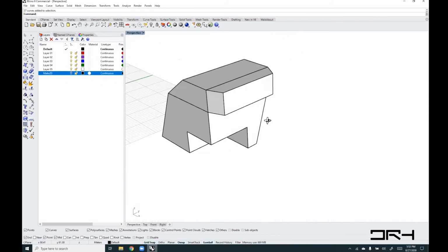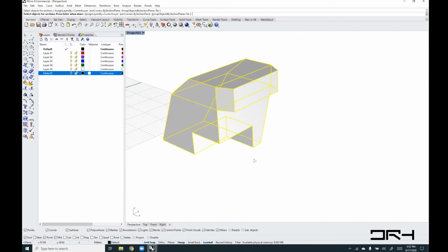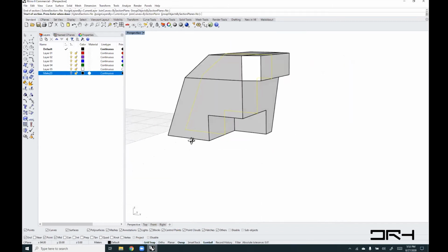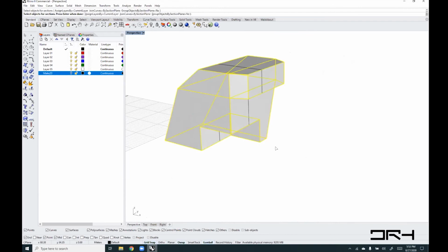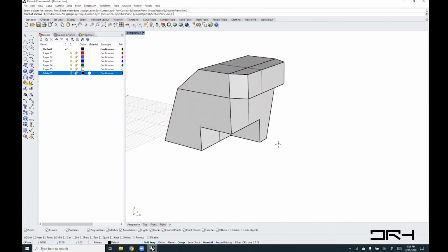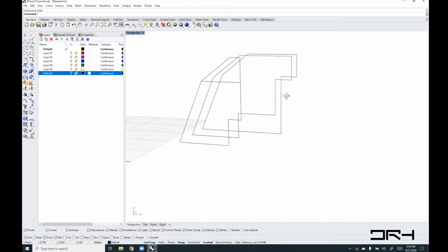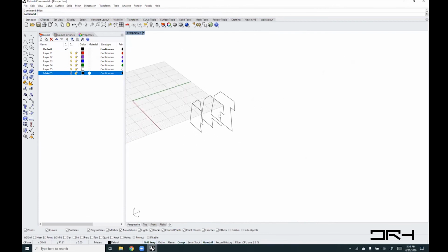Then you can use the Section command, where you can select your object and say, I want to section through there, from this line to this line. But I want multiple sections. So you can do start, end of the section, and then start, end of the next section, and so on. And that extracts all the different sections through your object. So that's the Section command.